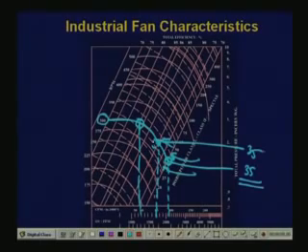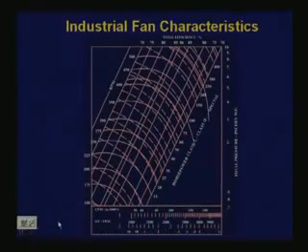This is the 30 curve, this is the 40 curve. It is actually a nonlinear variation, because from 50 to 60, 60 to 70 it is gradually getting closer. So this is something like 31, 32, slightly reduced. This is how you get those figures from an actual pump characteristic.